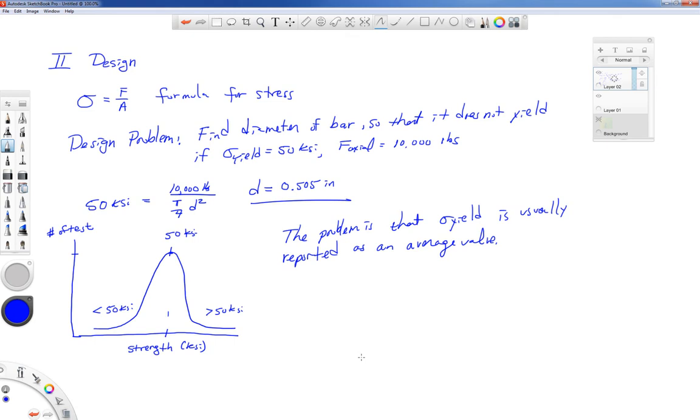That's usually an extrapolation from more regular users, but the idea is they can build in some extra safety, while still recognizing that there's going to be some customers that may push their vehicle to very extremes, and they can't design for every situation, but they'll do the best that they can. So this is sometimes known as a load factor and resistance design approach to structural design, and it's a great method. Now, in our class, we don't have a background in statistics, so we're going to take a slightly different approach to this called the safety factor approach.